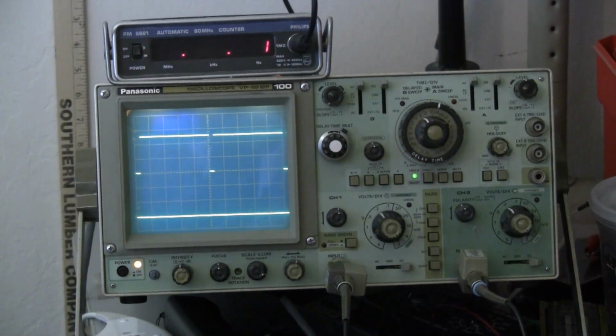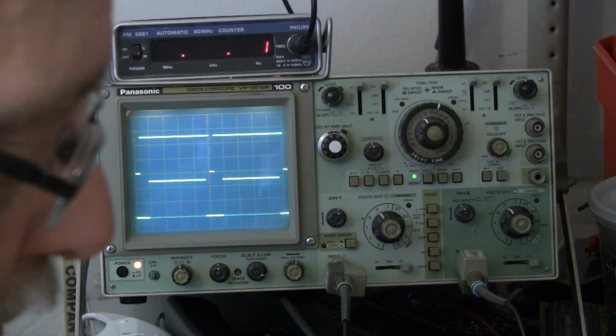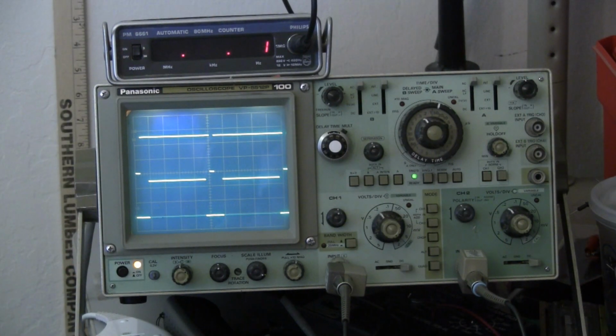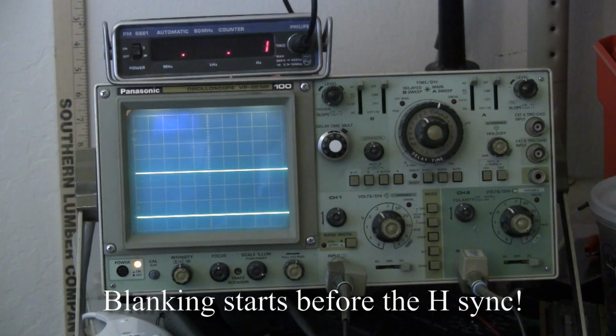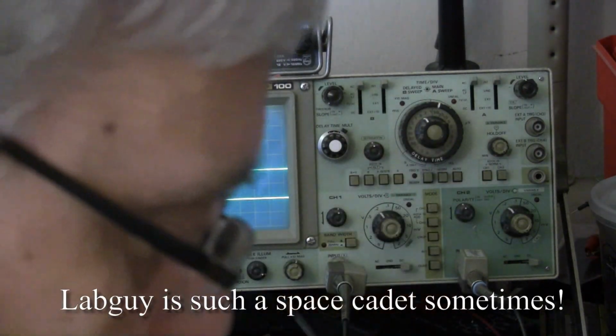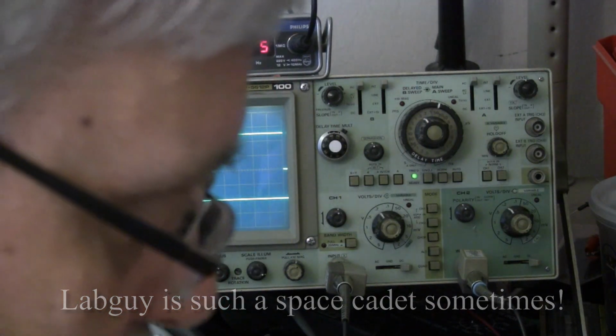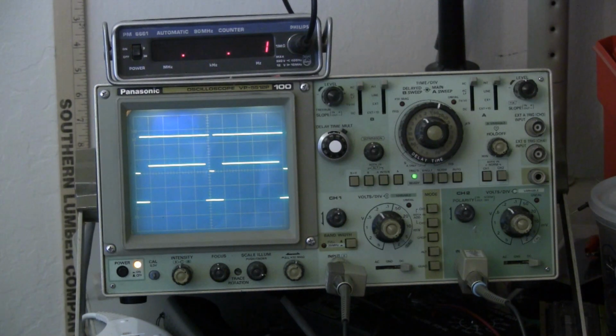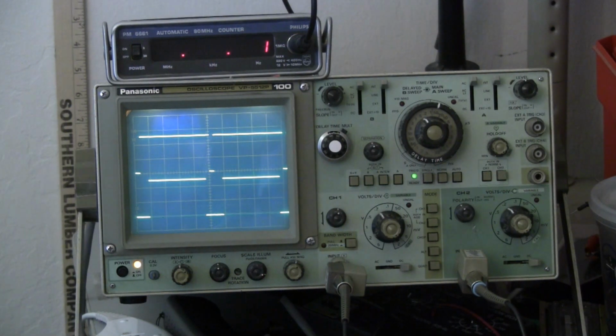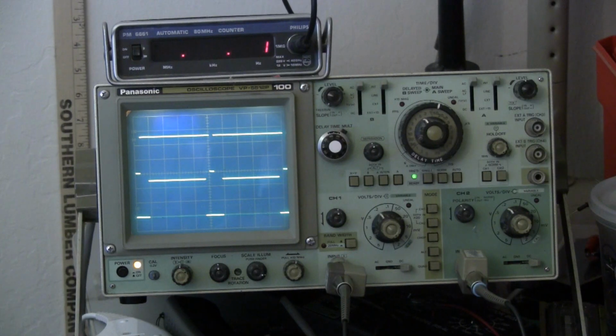There's the horizontal sync, and on the bottom trace will be the horizontal blanking, which you notice is wider than the sync. It starts a little bit after the sync. I'll try to reposition this a little so we can see the difference. I've overlapped the pulses a little bit. The sync pulse is the upper trace, which is narrower than the blanking. During the period that the blanking pulse is high is the period of time when the picture will be read out of the image memory. The upper trace, the sync pulse, is what tells the horizontal scan in the camera to start another line.